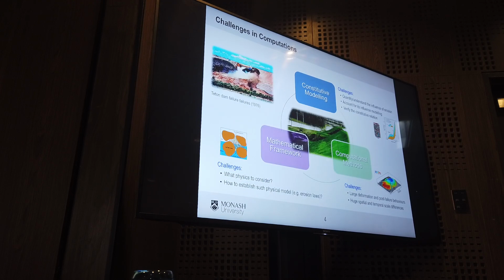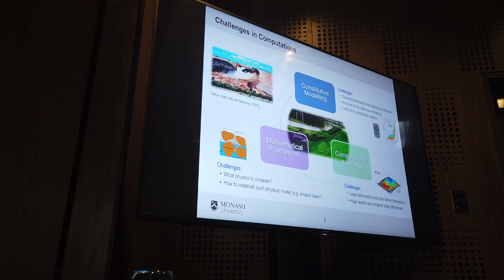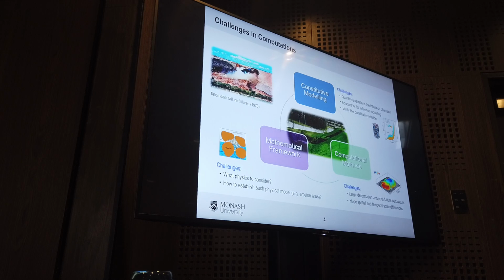In order to develop a computational model, normally we require three key components that include constitutive modeling, basically describing the mechanical consequences of internal erosion. We need to look at the mathematical model, basically the governing equations. Within this community, you see a lot of Navier-Stokes equations to describe the fluid flows.